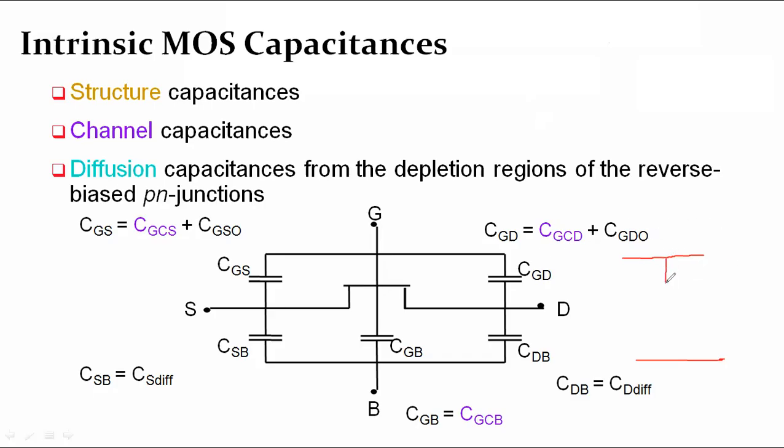First is the polysilicon, followed by the P diffusion, followed by the N diffusion. Then consider the polysilicon layer. Then we have one more polysilicon, and this entire thing is called a transistor. P transistor, below is the N transistor. Here we have to define a contact cut through the input. Here this is a simple stick diagram.